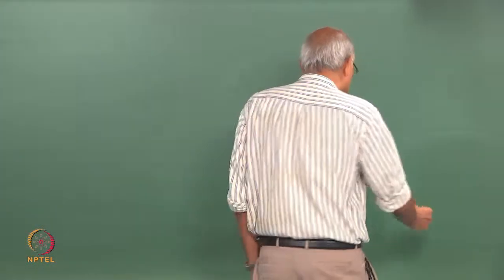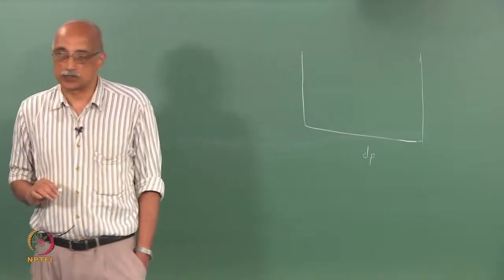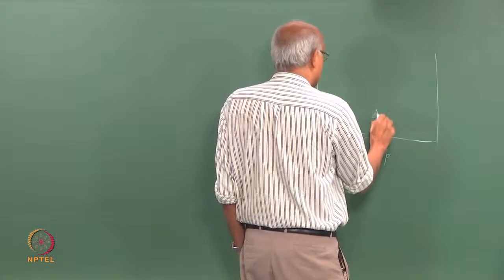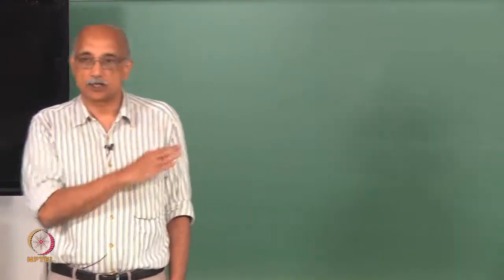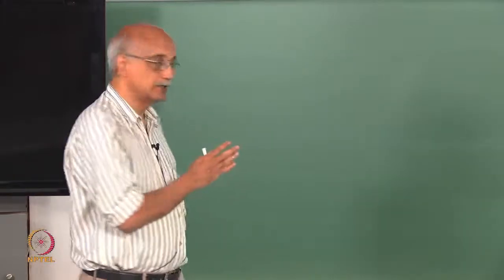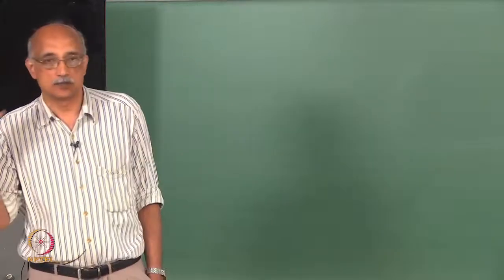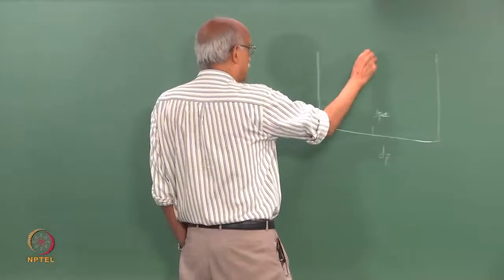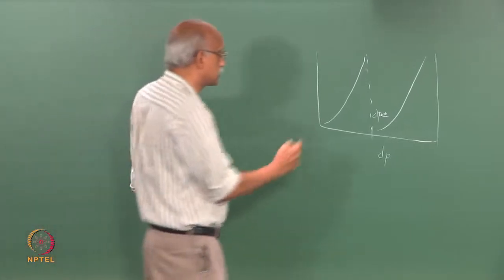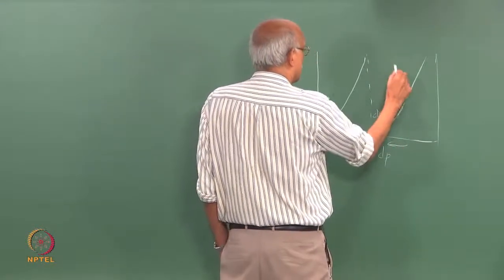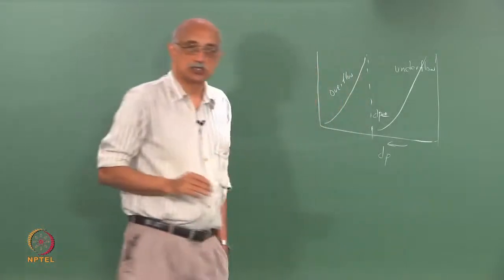If you look at the way a screen works, suppose you have particle size on this axis, there is something called DPC, which is the critical particle size, or it's a size that separates the underflow from the overflow. The implication is any particle that has a size that is smaller than DPC will be passing through, and any particle whose size is larger than DPC will be retained. So, if you plot this in an ideal screen, you may have two separate curves, let us say that size is increasing this way. This is underflow and this is overflow, and these are the size distributions in the two.